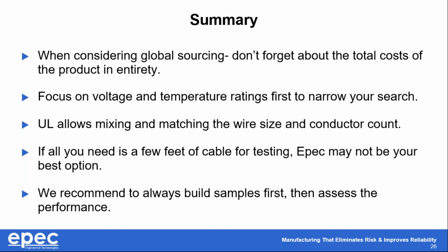Next, it's important to note that UL does allow the mixing and matching of wire sizes and conductor counts such that there's no violation of the temperature, voltage, or flammability ratings.